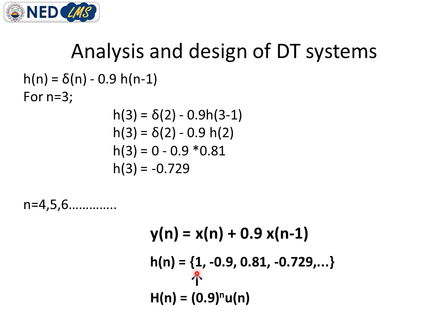But you can notice that the impulse response is this, and the generic representation of this impulse response is this. We can represent it in the generic form also. So we can expand this function to obtain these sample values or this sequence. One interesting thing we can notice from this sequence is one value is positive and the next value is negative, and again the next value is positive and the other value is negative.